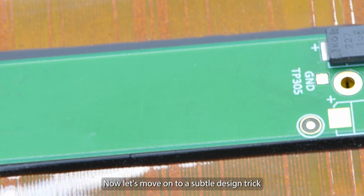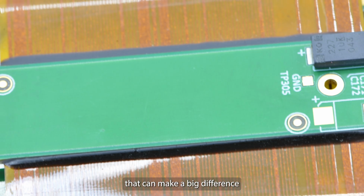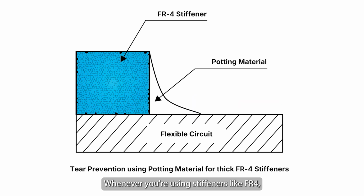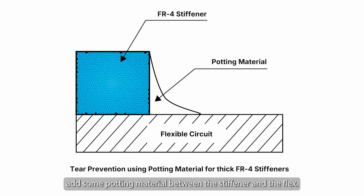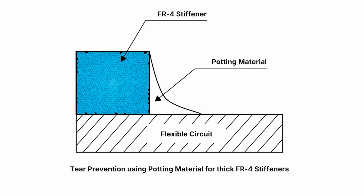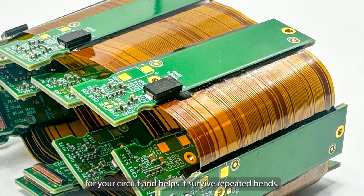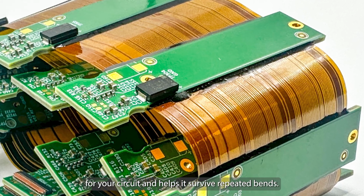Now let's move on to a subtle design trick that can make a big difference when combining stiff and flexible areas: strain relief at rigid sections. Whenever you're using stiffeners like FR4, add some potting material between the stiffener and the flex. This softens the transition, like shock absorbers for your circuit, and helps it survive repeated bends.